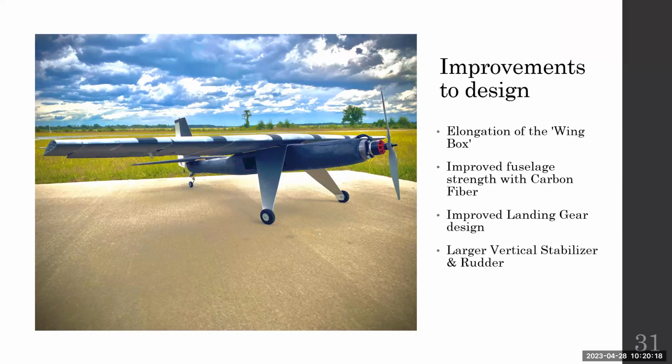You're on the right track. The key point I was trying to get to is that you have a high pressure region below the wing, which is a lot harder to disturb the actual flow of the air, versus low pressure on top. You disturb that, it creates flow separation, a lot of drag. Just a conceptual question: I think your guys' landing gear design is really smart, very intuitive. Especially the second design, making it one piece and having it attached to the top of the fuselage as opposed to the bottom. So good job on that.